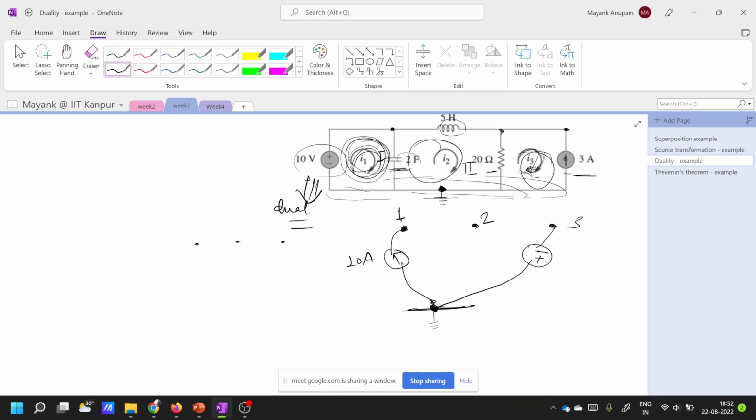So this current is opposite to this convention. The voltage source will be opposite because of the direction of current in the third mesh. The mesh current convention that you have chosen here is opposite to the current source here, isn't it? So that is why you have to change the sign here also. Am I clear? Yes, sir.